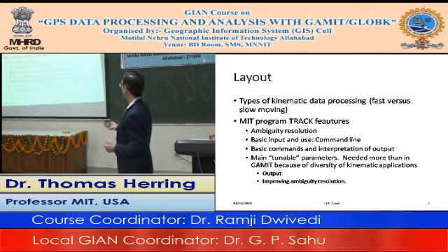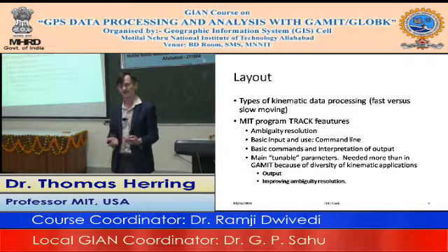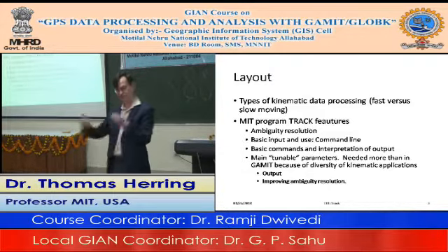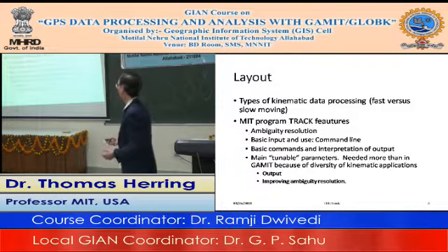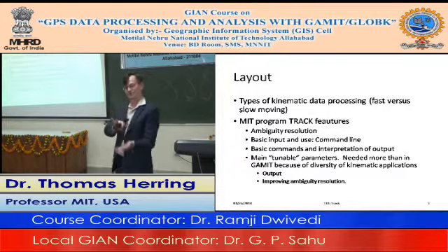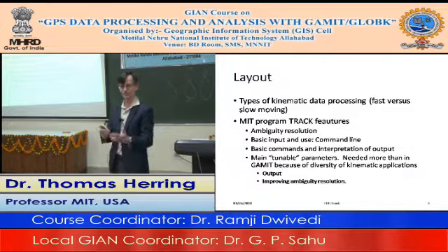So this kinematic processing, we heard the lecture this morning about this, and the way this is implemented in the MIT software is a program called TRACK, and it's a post-processing program. So the idea is you collect your data and then you come back and look at it. We'll talk about how it does the ambiguity resolution, some basic use of its command line, and some of the tunable parameters in this program. And again, this whole lecture will probably be most useful later on, if you decide to start using TRACK to process data.